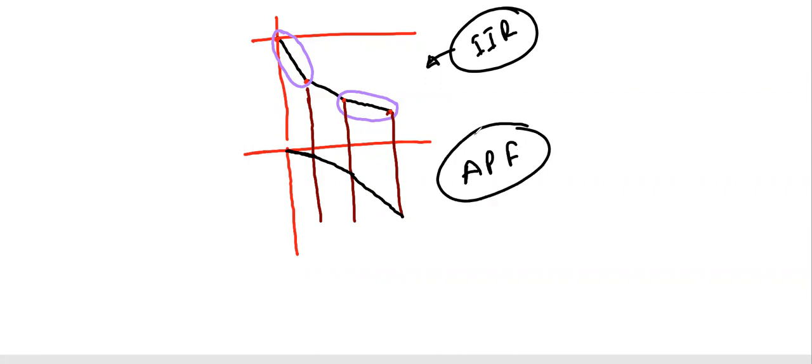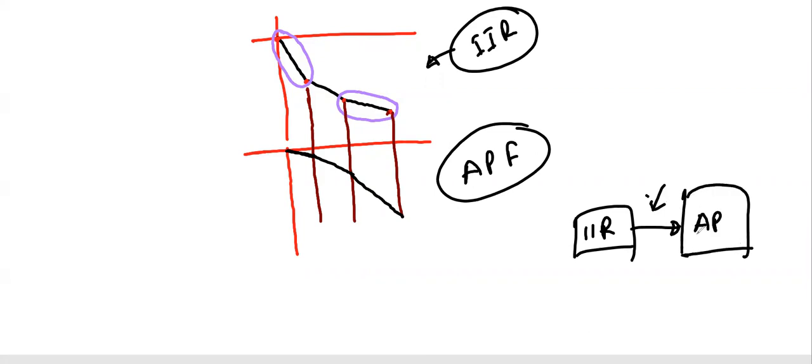We have done these things, and this is for the conventional IIR type filter, and this is for the all pass filter. As we can understand, in the case of the IIR type filter, we get the output, and that is exactly okay. No problem with the output, but the problem is the phase response. That's why we are designing an all pass filter. What does the all pass do? It will actually pass everything, but we want to control the phase of the IIR filter, and that is the